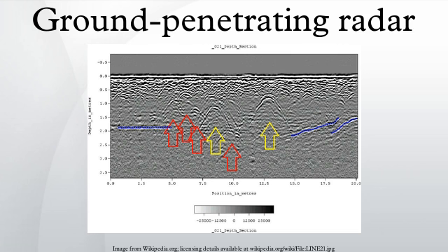Time slicing has become standard practice in archaeological applications, because horizontal patterning is often the most important indicator of cultural activities. Limitations: the most significant performance limitation of GPR is in high conductivity materials such as clay soils and soils that are salt contaminated. Performance is also limited by signal scattering in heterogeneous conditions.